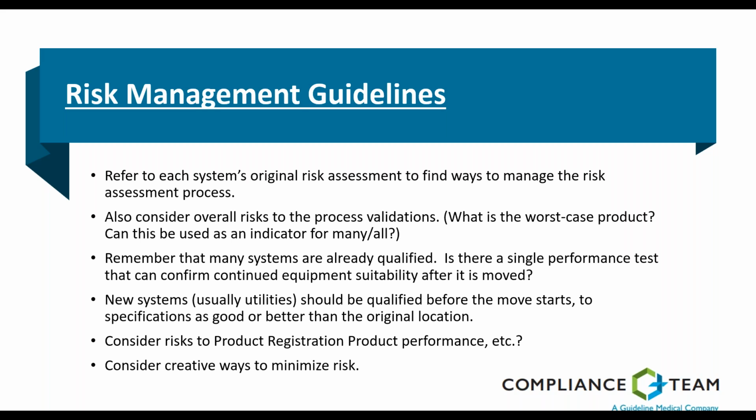And can you put that in your validation master plan, understanding that the worst case process that takes place on this piece of equipment is this one, and if we qualify it for that, we know that it's suitable for its intended use for the others. So there may be just one performance test that is indicating of that equipment's continued suitability.